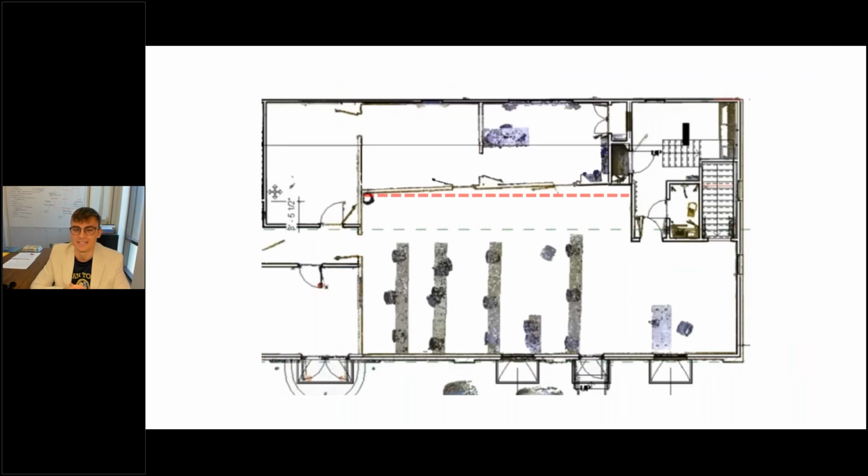There's also the 90-degree rule. This is a concept I'll cover more in the modeling section, but essentially it refers to whether the client needs as-built information or normalized information. As-built is needed if you need the model to be as accurate as possible. Normalized information, for example, when you need the model to play nice with design tools that maybe expect things to be straight and parallel and 90 degrees to one another. So then you have to normalize.